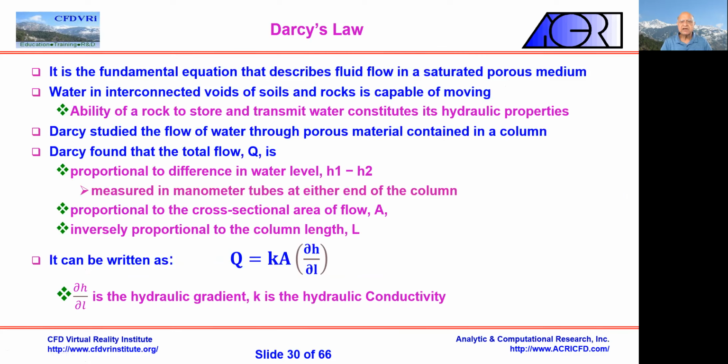So firstly, the fundamental equation describes the Darcy Law, which essentially describes the saturated porous medium. Okay, so we have water in interconnected voids in the soil, and rocks may have fractures, so the water moves through that based upon the pressure differences. Okay, so the ability to transmit and store water in the rock constitutes the hydraulic property.